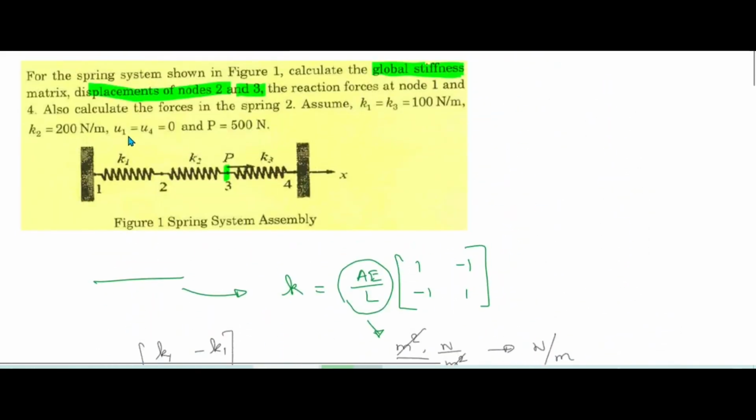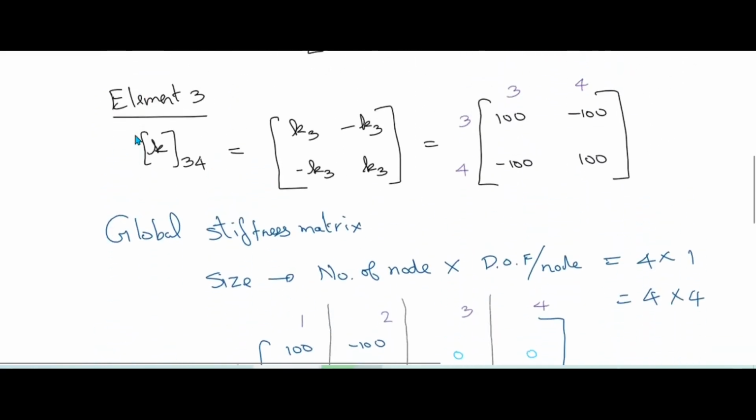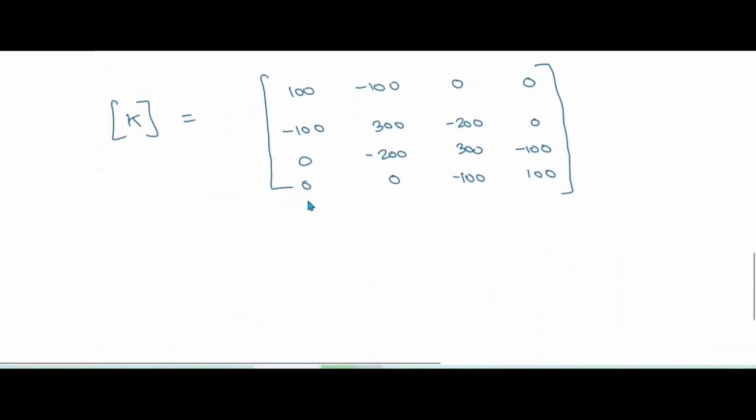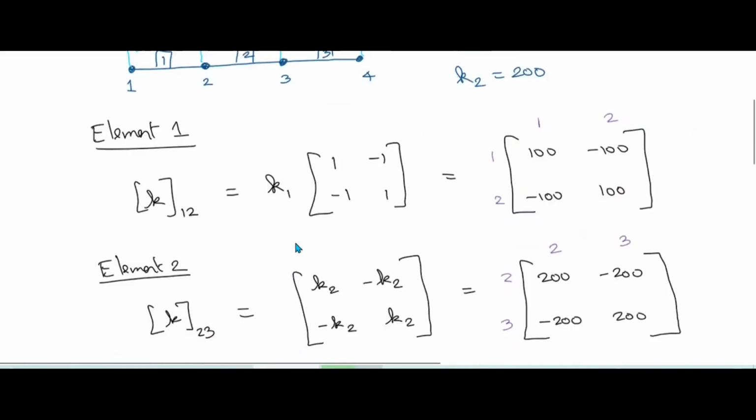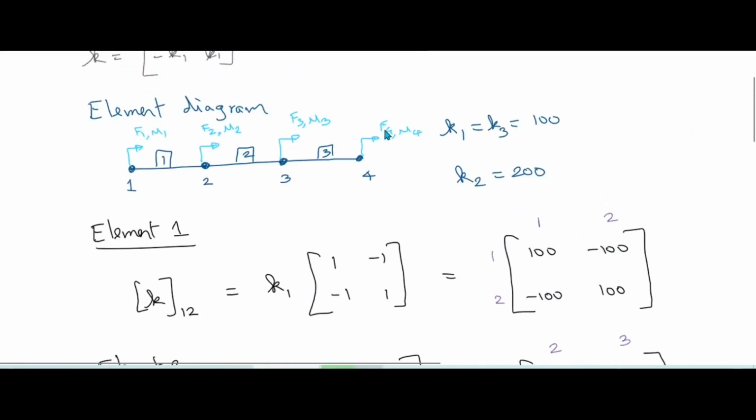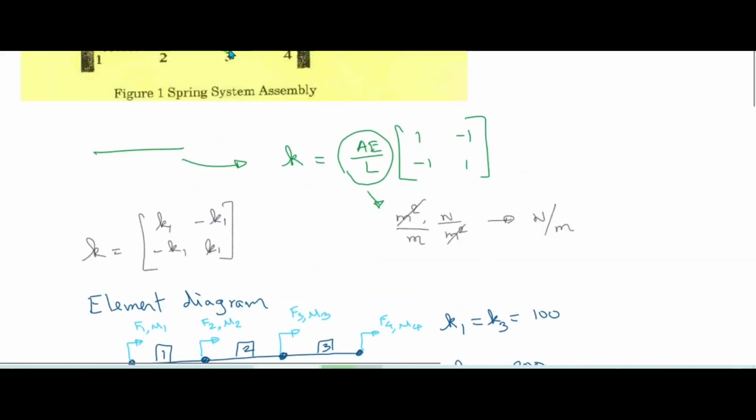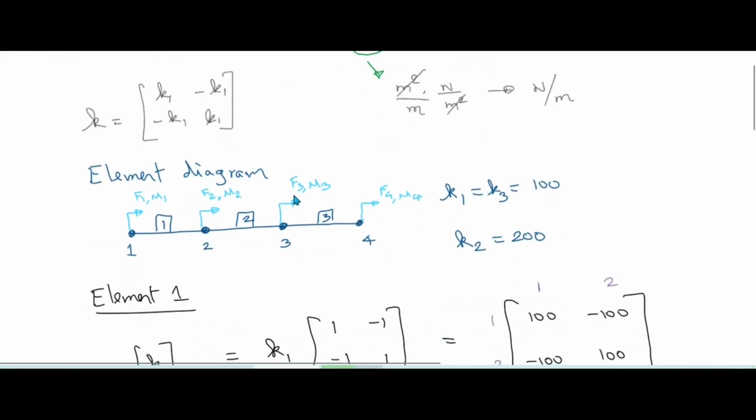The next step is I have to identify what is my displacement. To identify the displacement, you know that force is equal to your stiffness matrix K into your displacement U. So input force is equal to your stiffness matrix into your displacement. So let us identify what the forces are. The force will be in terms of F1, F2, F3 and F4 in a column matrix. Since we have force only at nodal point 3, we have only F3.